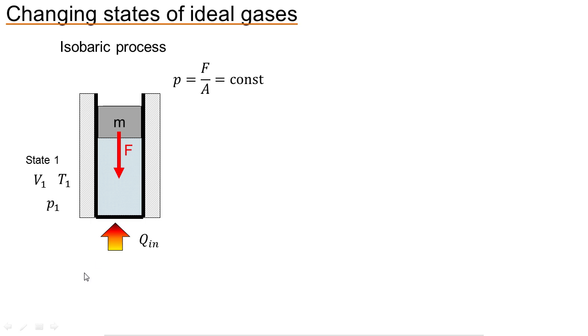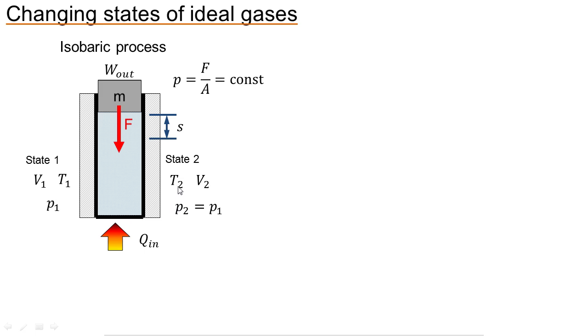If I add some heat to this gas here, the piston will move up. The gas will expand while applying heat, and the piston will move up. So I will move the force in the direction of the force, and this means I will put work out of this. I can describe the new state of the gas now with a new temperature.